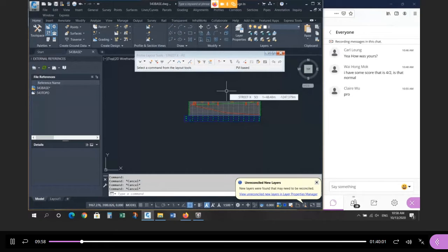And it is common practice to keep this part of it simple. You'll see all we really want to do is have the finished ground. I don't need all the underground layers. For estimating purposes, I'm not going to use the corridor. I'm just going to use it for the geometry I need to go forward. The corridor is a requirement to do all your grading design and your servicing design. You'll see how that all fits together in the second half of the course.